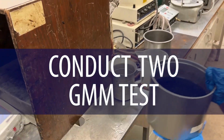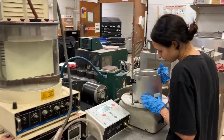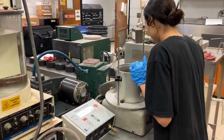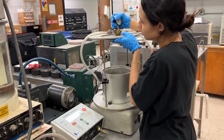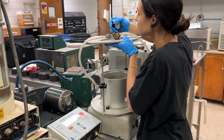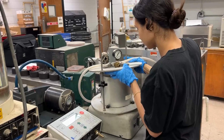According to the application of quality assurance specifications for asphalt concrete mixtures, these 2 tests will be averaged to report a single value. By conducting multiple tests and combining the results, we can increase the accuracy and reliability of our measurements by providing more comprehensive quality control over the asphalt mixture.